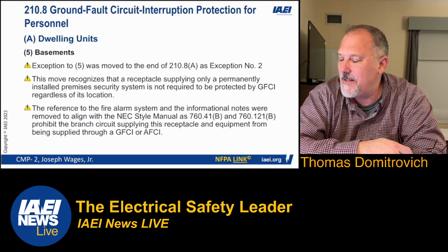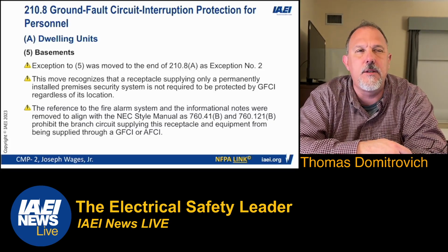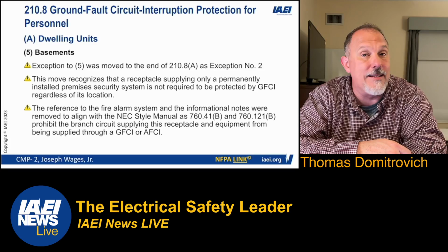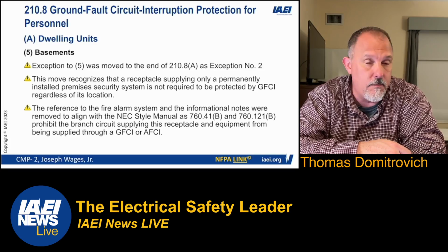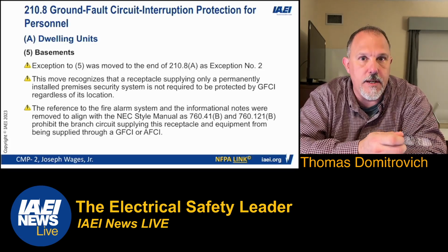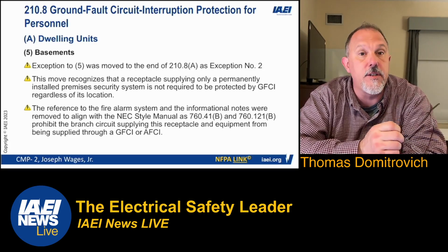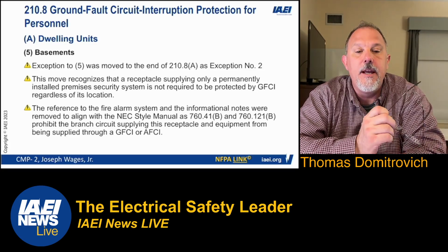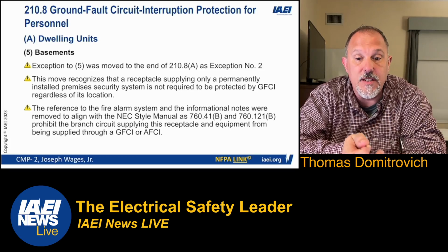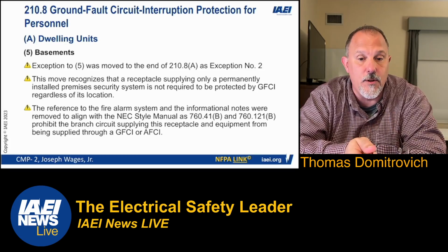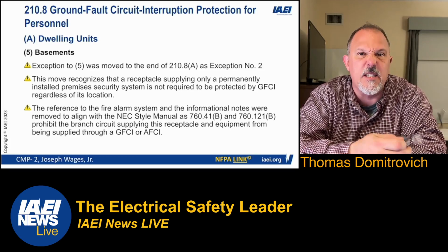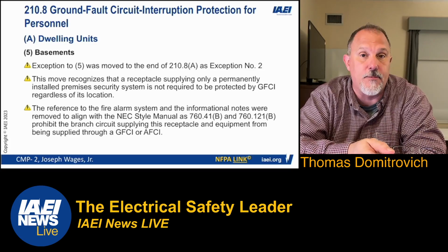So we said it doesn't make sense. I don't need to make the exception apply to any specific room. Not needed. So we removed the exception, we removed the reference to basements. The other thing we did was we removed the 760.120 fire alarm system exception, because it's already covered in chapter 7.